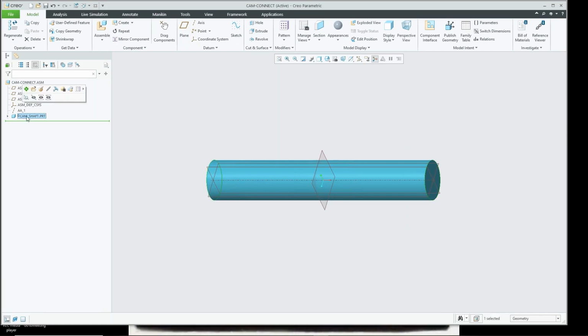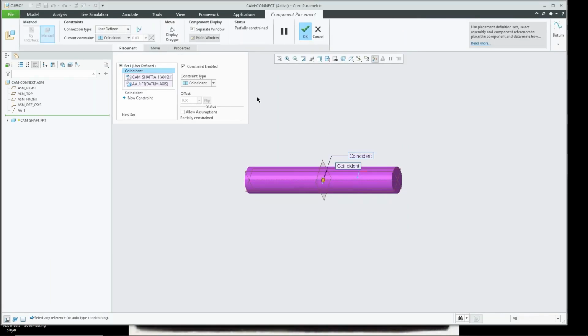Now with this, I don't know if you noticed, I've actually done regular constraints. I did not go in and create it with connections. I noticed this after I had done it. I don't want to go in and undo my constraints, but the benefit of this is that the references that I just used for these constraints are the same references that I would use for a pin connection.